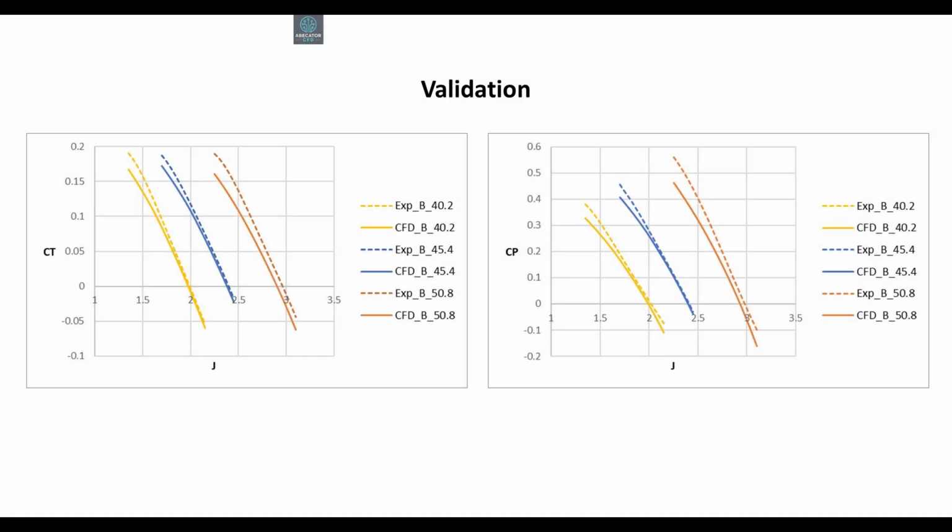I have performed this propeller simulation using exactly the same setup for several operating conditions. I also digitized the experimental data for the 1600 RPM operating condition from the NASA benchmark report, and I have provided these data for you as well. The simulation results show very good agreement with the experimental data. In other words, we have successfully completed a solid validation study.